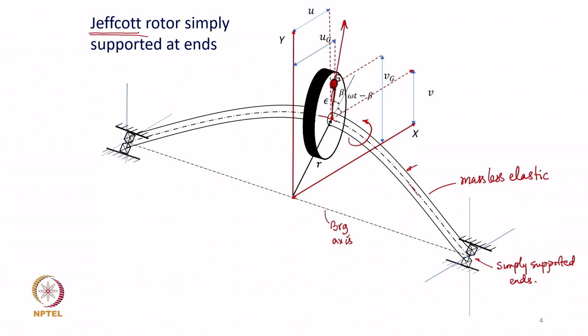So, as the rotor spins with certain speed, the centrifugal force because of unbalance is going to act on the axis of the shaft or the spinning shaft, and then it is going to pull that shaft outwards in the direction of the force, and the position of the disc center or the shaft center in the plane where the disc is located.